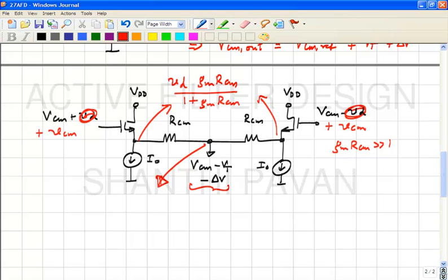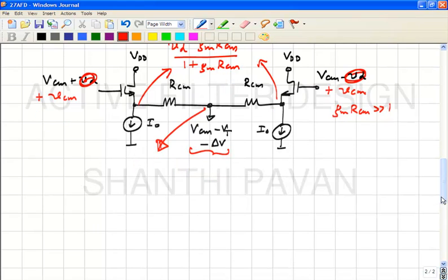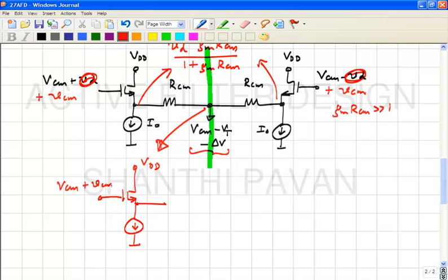No, both the voltages are the same. Correct? So, you can use simply half circuit analysis. What is the current? Both sides are the same. So, what is the current flowing through this way? No current. So, as far as the common mode response is concerned, it is equivalent to simply analyzing this half. If no current flows through the resistors, the drop across them is 0. So, all that we are interested in is finding VCM, the change in the voltage here due to this.